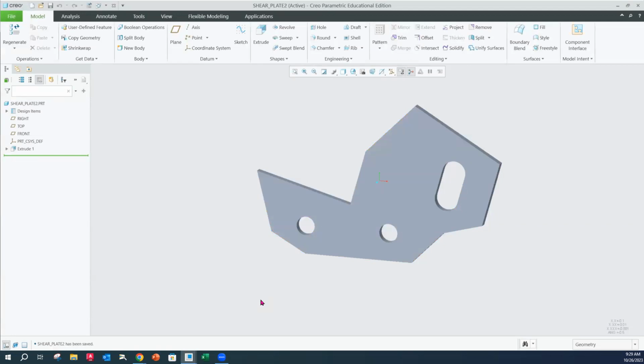If I leave it out there as an SEC file, as just a sketch file, I can't pull that up, believe it or not. It's just kind of something weird with Creo, I guess. We'll find little weird things along the way, but that's okay. We're working with it. And now that it's a part file, I can pull that part file back up and then I can change things about it. So if you did want to pull that part file and go back to your sketcher, notice that we have an extrude here over in what we call our design tree. We'll talk more about this as we go along, but we're just focusing on sketching right now.